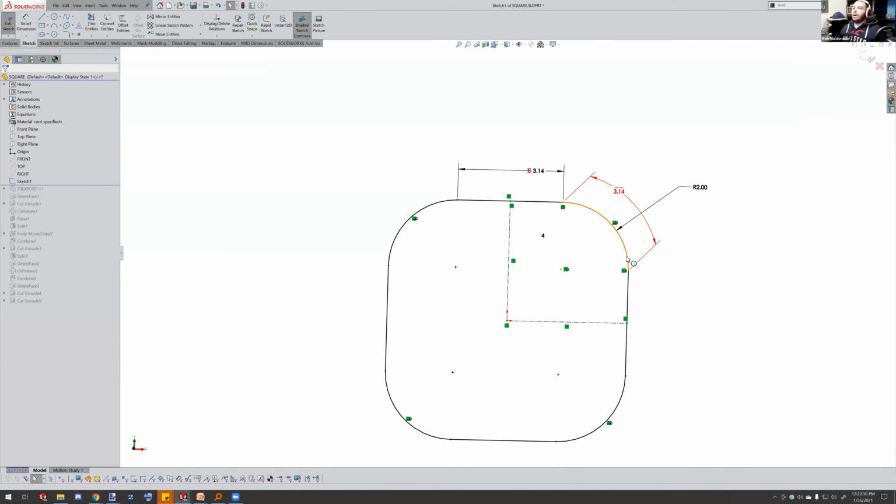But before I did that, this square gear, my technique was, the square has rounded corners, and I wanted the length of this rounded corner to be the same as this straight section. When a corner comes into contact here, it'll roll along the straight edge, just like a rack and pinion. But I needed to make sure they're both the same length.